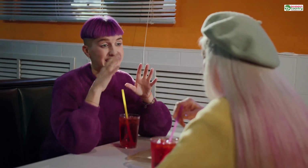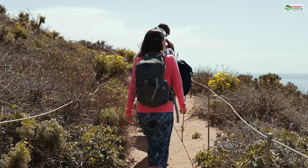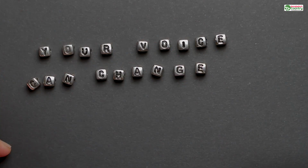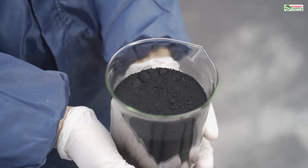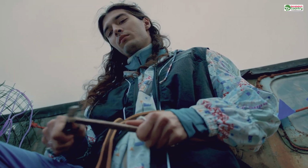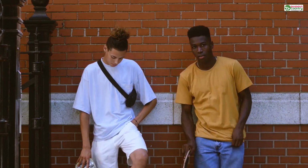Okay, so you're sold. You open your software, you find the hollow button, you click it, and you've just created a digital time bomb. Because you missed the most critical step. You've created a sealed container. A beautiful eggshell with no way in or out. If you send this to a powder-based service like SLS, all the loose, unsintered powder that gives the model its shape during printing will be trapped inside forever. You'll have a model that's supposed to be light, but it's full of powder, rattling around like a maraca. You can never get it out.